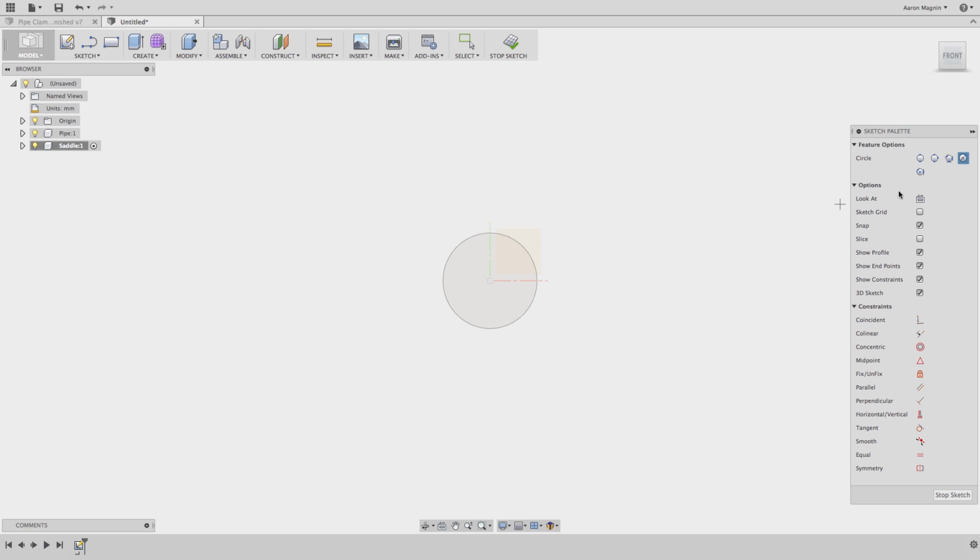Now, I have actually 5 different ways of drawing circles. I could use a 2-point circle, I could use a 3-point circle, etc. I can do a lot of different things, but the center point circle is the one I'm actually looking for, and what I want to do is place it at the center point of the entire design, sketch it out to copy essentially the existing sketch there, and that's the start to this sketch.